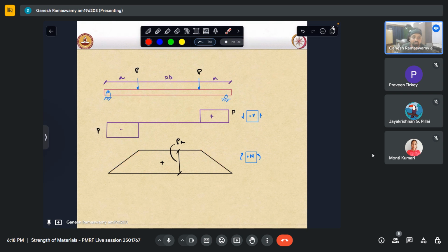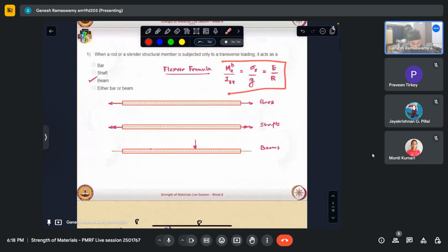We want the slope of the bending moment diagram to be zero in order to apply the flexure formula with mathematical rigor. In other places, it is just an approximation. We are just approximating the results, but that is reasonably acceptable in this course.